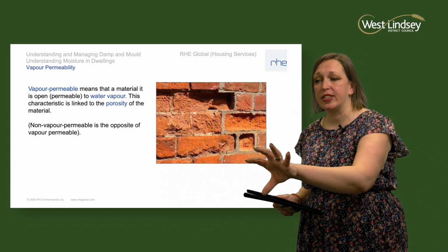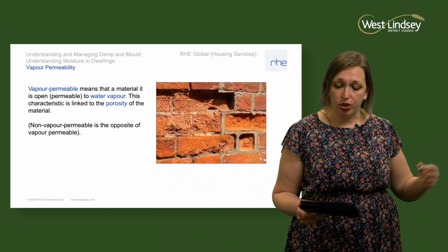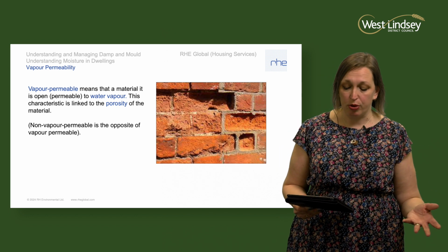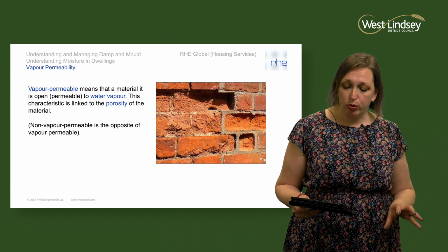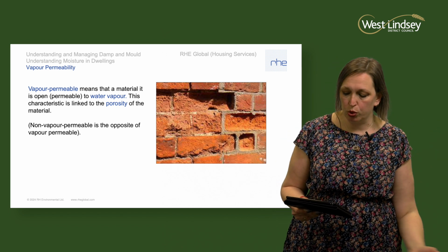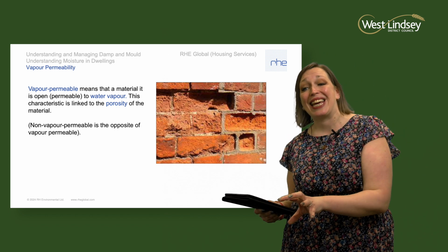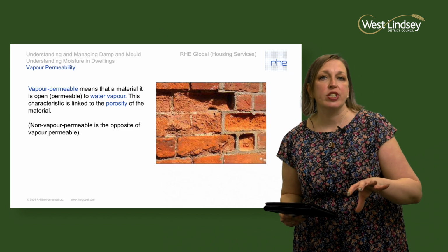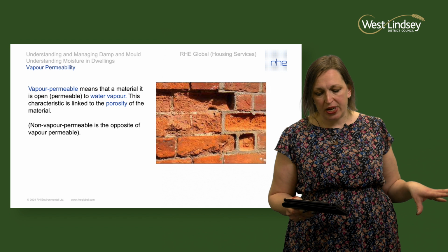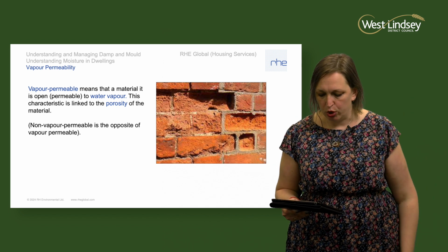So in this picture, the moisture hasn't been able to move through the cement mortar, so it's gone through the bricks, so it's damaged the brickwork. On top of that, cement mortar doesn't really bond well to lime mortar, so that can also trap moisture within the bricks, leading to frost damage. So in this particular case, all the repointing that had been done in cement needed to be scraped out, and that needed to be repointed with lime mortar to maintain that moisture route.